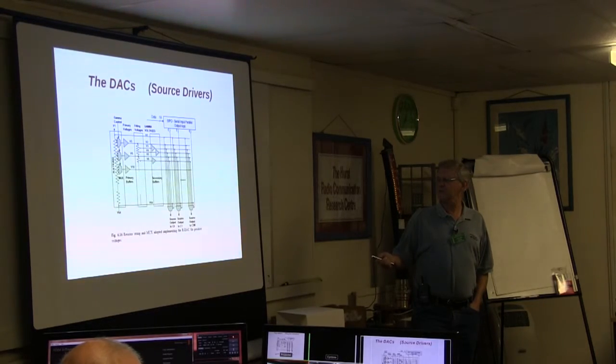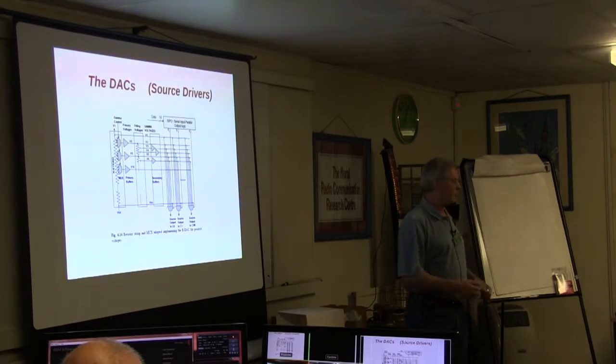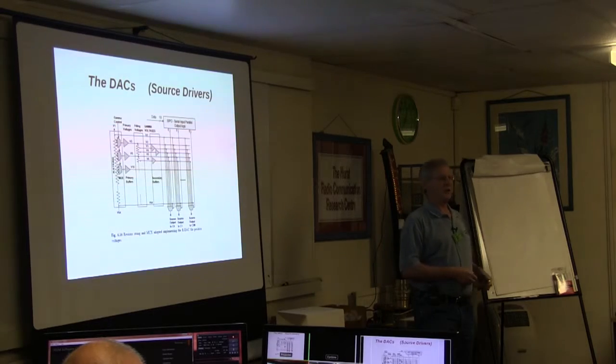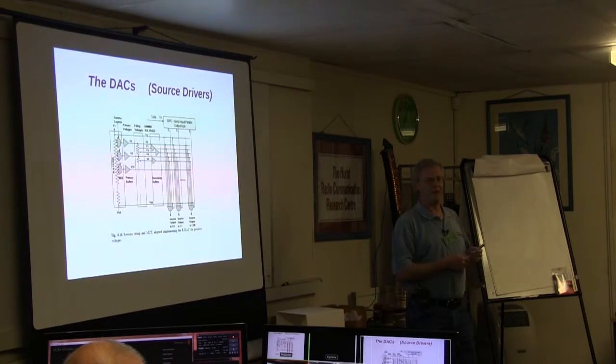And something I don't show you there, there's another amplifier in there which is the common point for all the capacitors out on the screen, and they call that VCOM. And that one, nowadays it can typically require 1.5 amps on it to charge these things fast.